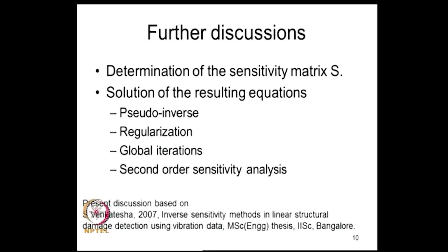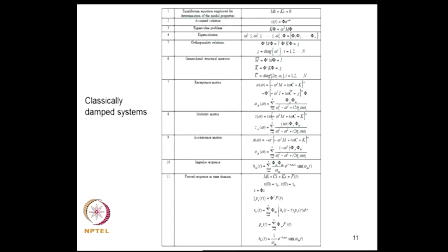Now, to implement this method, clearly we need to discuss how to determine the sensitivity matrix S and how you solve the resulting set of equations. There are various issues like pseudo inverse, regularization, global iterations, and we may like to include second order sensitivity terms in our analysis and how to proceed if we do that. So, the present discussion is based on a MSc thesis that is cited here by Mr. S. Venkatesh.